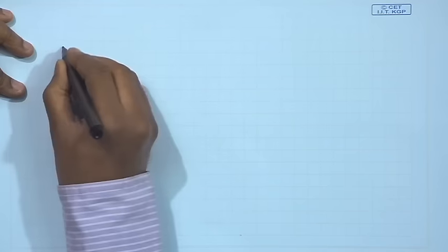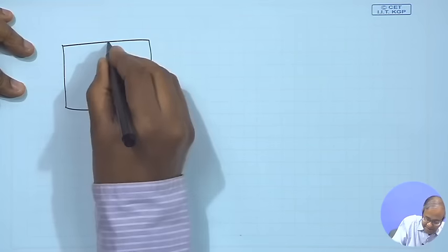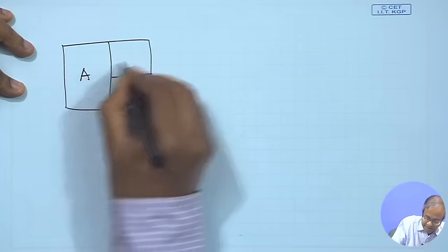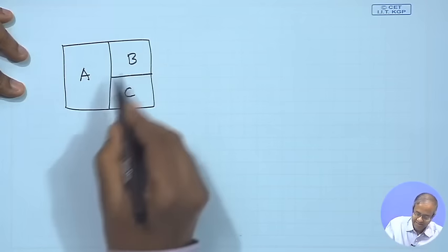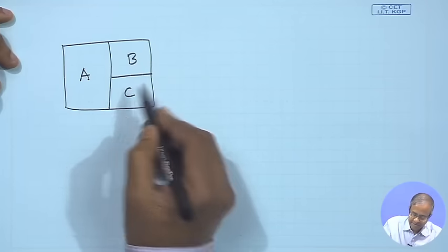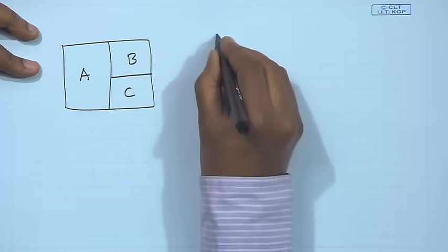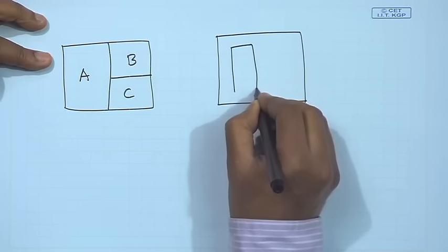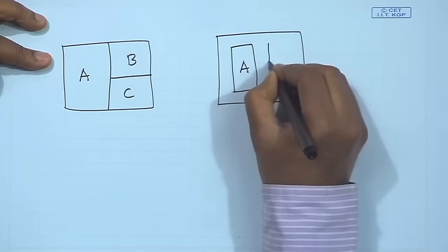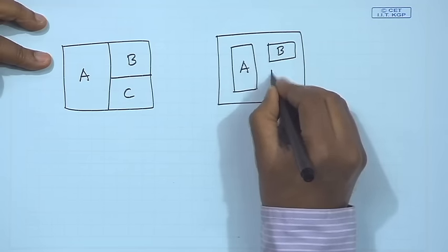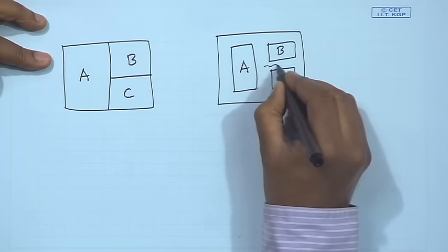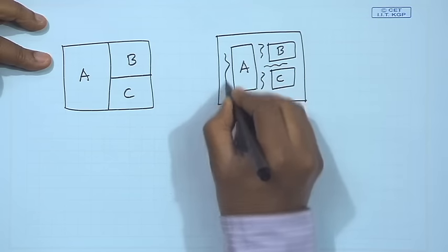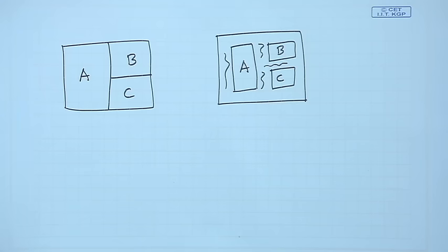Like an example, now in floor planning I can say that I have 3 blocks A, B and C, which have to be placed like this, B on top of C and A to the left of B and C. But in placement, here I will specify it like this, this is my block A, this is my block B, this is my block C, and there is some space in between I have kept for interconnections. This is the output of the placement problem, right. So, this is the main difference between floor planning and placement.